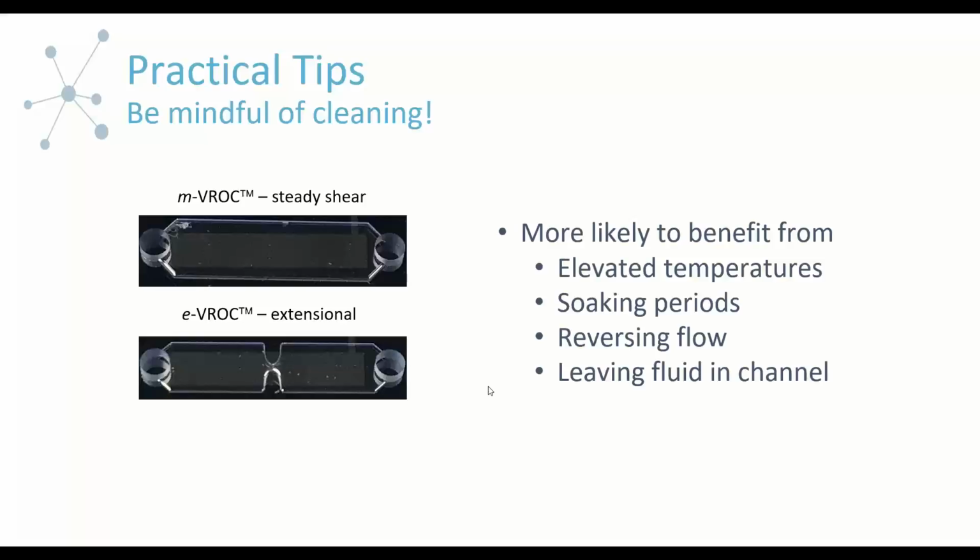So just some tips if you're working with this, or think you will be working with it: in the cleaning process, it's going to be a little more beneficial, perhaps, to use elevated temperatures if that helps with solubility, and then also reduction of the viscosity of the fluid that you're trying to clean out.